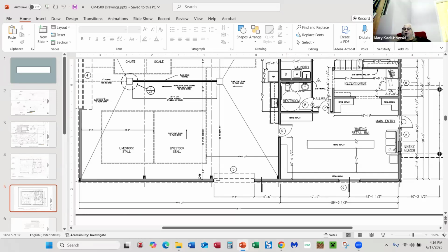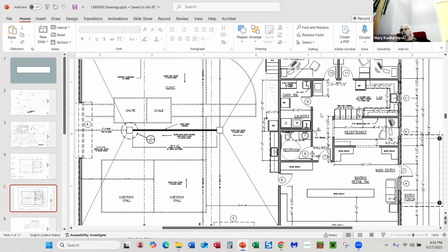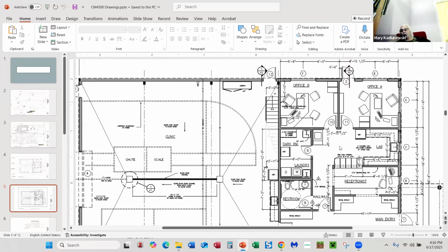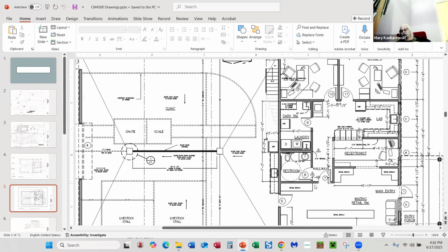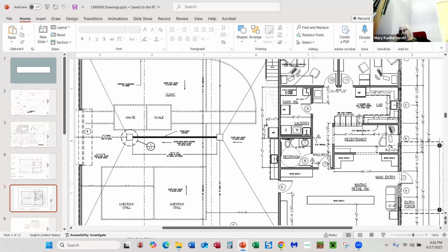So, walk around. When you come in the door here, you're going to want to turn the light on, right? So you'll need a switch here. If you're coming up this hallway because you've come in this back way, you're also going to need a light switch here, right? And a switch here. Since you have 3 switches, you're going to need a 4-pole switch. So you'll put an S for the switch symbol and a 4.